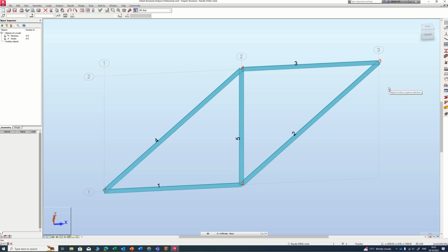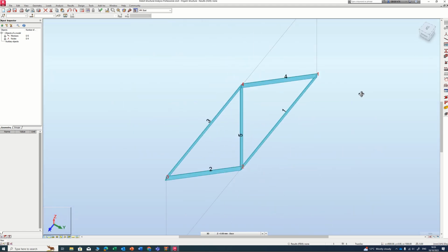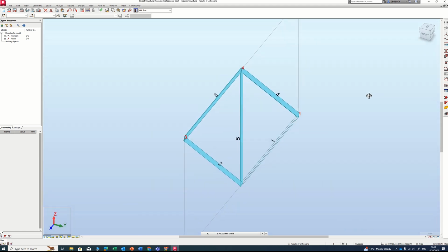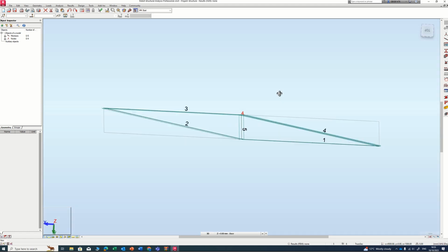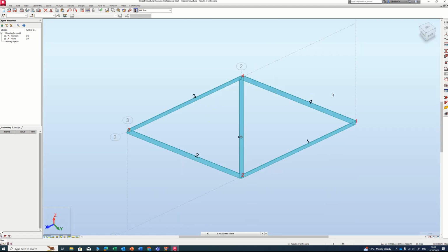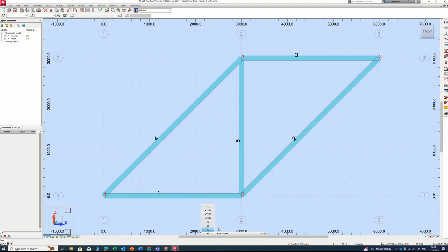So basically, you hold the shift key, press the wheel in the middle of the mouse, and hold both. Then you can turn your mouse and rotate this structure to the location you want, and then release. Okay, once done, you can switch back to the coordinates. The coordinates we have is xz, 2D coordinates in here. So we click on this one, and it comes back to the original direction.